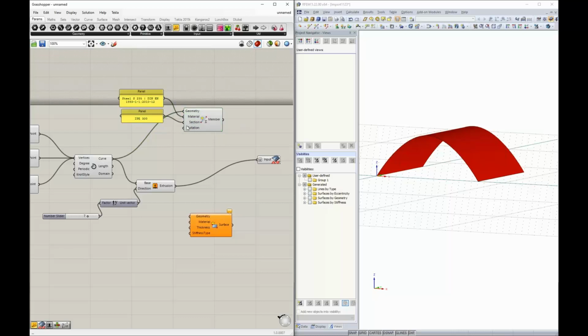Of course, we can change the rotation of a member. We can do it again maybe using a panel. Let's say we enter values from 0 to 90 degree. So here I can switch between the values 0 and 90. I could theoretically connect now this slider with the rotation. There's just a small issue. We expect the rotation in radians.